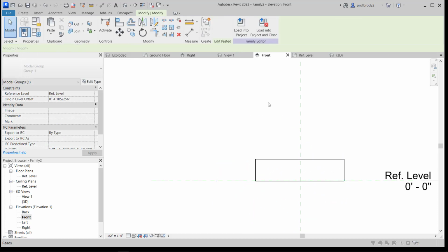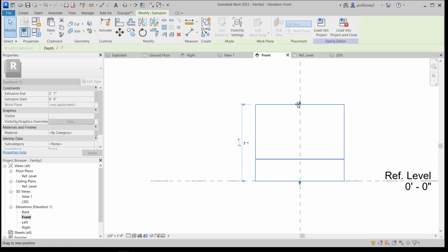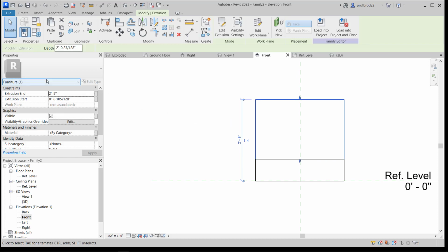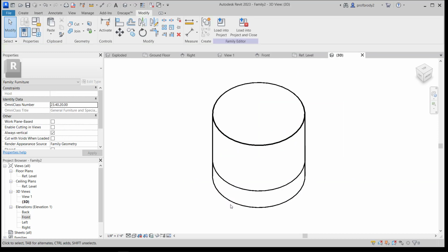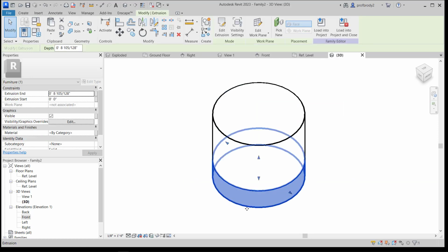So now I have two of them, and I can just stretch the mass up for the top of the ottoman. Again, your modeling technique, I could have probably done this as a revolve as well. So to associate a parameter with one or another pieces, and maybe I want independent control of these two pieces, that's why I made them as two pieces,